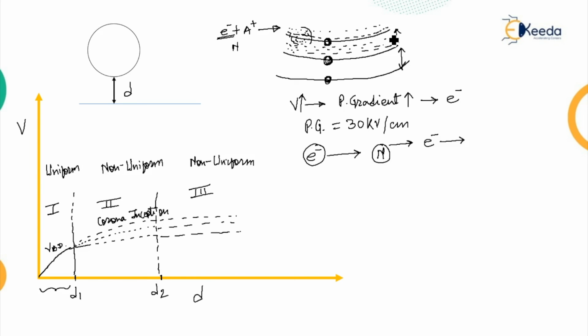So this is all about the corona discharge. I think all of you have understood what is meant by corona discharge. Corona discharge is the kind of discharge which appears in the form of light, which is referred to as corona. We have arc formation, corona formation, and even lightning. All these three effects are the result of ionization between the gap of charged elements or charged particles. Like lightning is formed between the charged clouds, corona is formed between the charged electric lines, and the arc is formed between the charged electrodes in, say, circuit breakers.